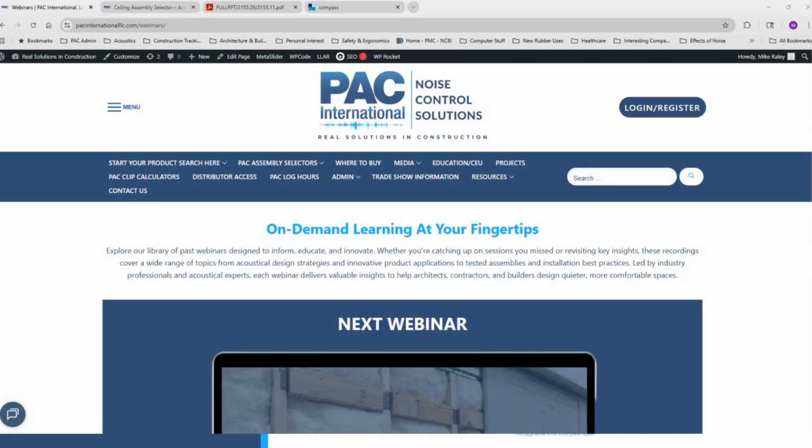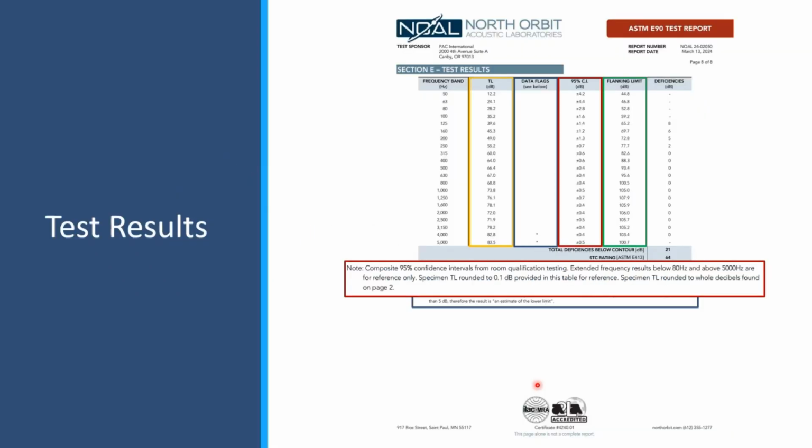E336 is, just for some context for everybody, the ASTM standard for doing airborne sound isolation in the field, whereas E90, the one I've been talking about, is the standard for doing it in the lab. Okay, nothing in particular. So in the field, there are a number of different metrics that you can get: ASTC, NNIC, and NIC. And basically you measure them all about the same way, similar to how you do an E90 STC test too.